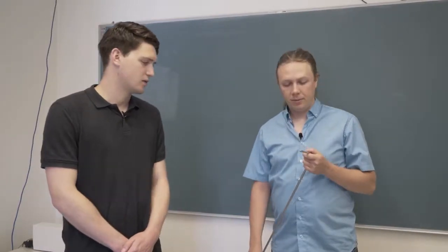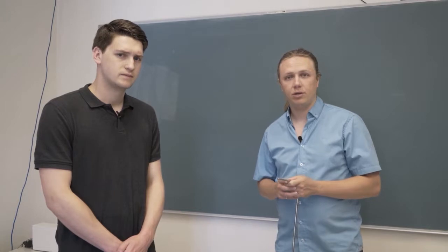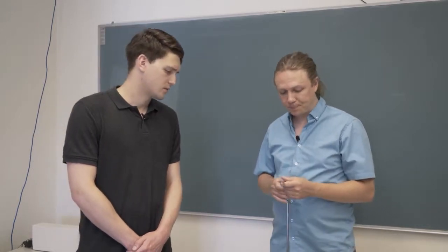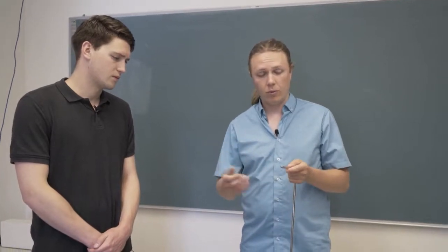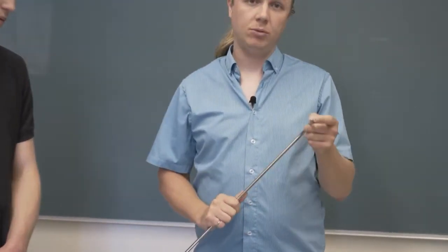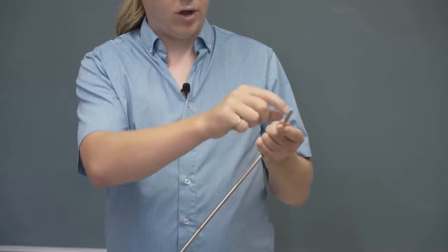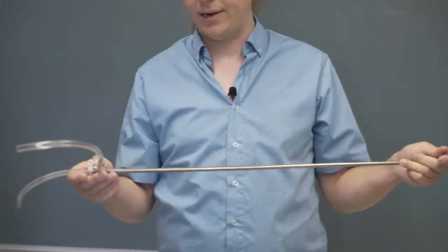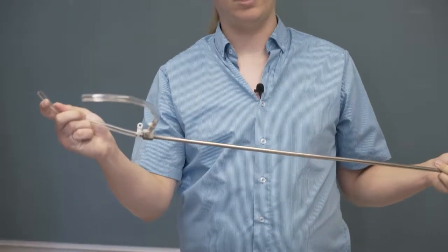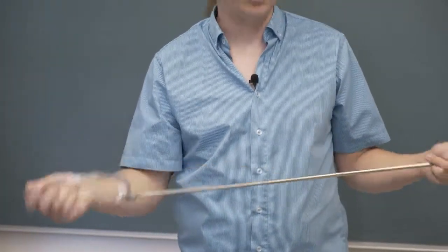Sure. So fundamentally, pitot tubes are measuring the difference between the total and the static pressure of some flow field. So if we look closely at the probe I have here, there are two important parts. The stagnation port is on the front of it, or on the tip of the probe, and that's a long tube that runs all the way through this entire apparatus and pokes out the bottom. So we can connect this to a transducer or to some kind of measuring device to sense the pressure.